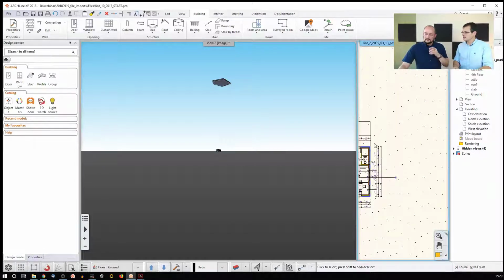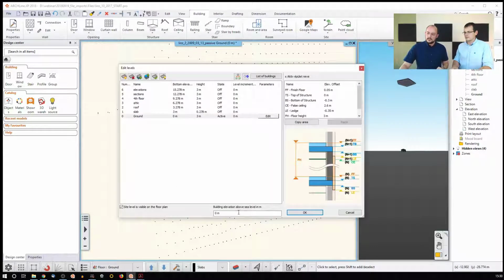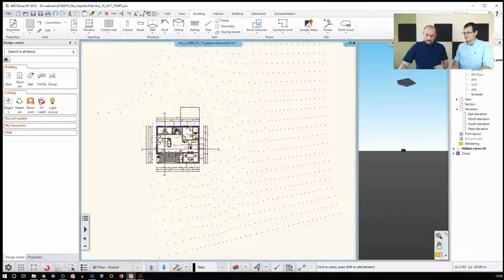Yes. So to do that, what you need to do is just to enlarge the 2D content and open up the floor management dialog, and this is where you can fix it. So if I just type 250 now, okay, and then I regenerate the 3D, then you will see at the right hand side that the building will disappear. And it will be pushed onto the... yeah, we see above, it's over there.